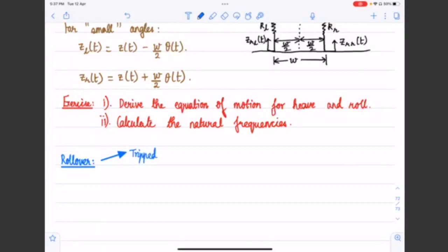Imagine that, let's say we are driving a car, and one side of the vehicle, one tire hits an embankment or another projection on the road, and due to that it trips over, right? So there are lateral forces, lateral accelerations that come about, and that's what is called a trip rollover. So another class is what is called the untripped rollover.